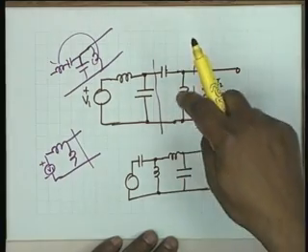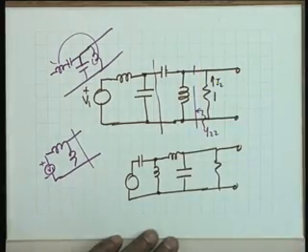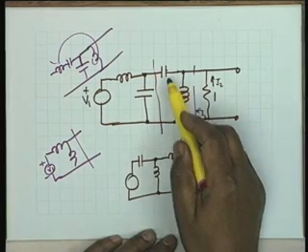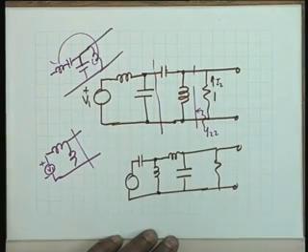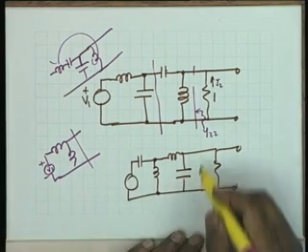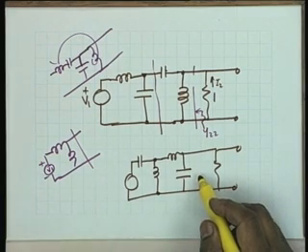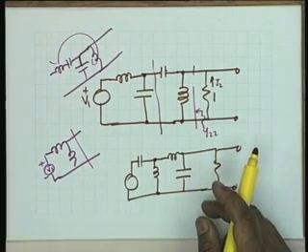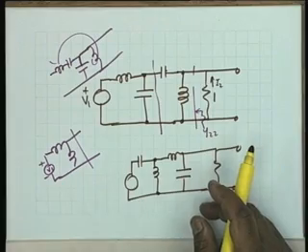Now, go back to this question, how do you develop Y22? Obviously, 2 steps of Cauer 2, then change over to 2 steps of Cauer 1, right? If you want to develop this, for example, then 2 steps of Cauer 1 followed by 2 steps of Cauer 2. You have to be very careful. There is a blind method also. You don't know Cauer 1, Cauer 2. You continue to remove the poles.